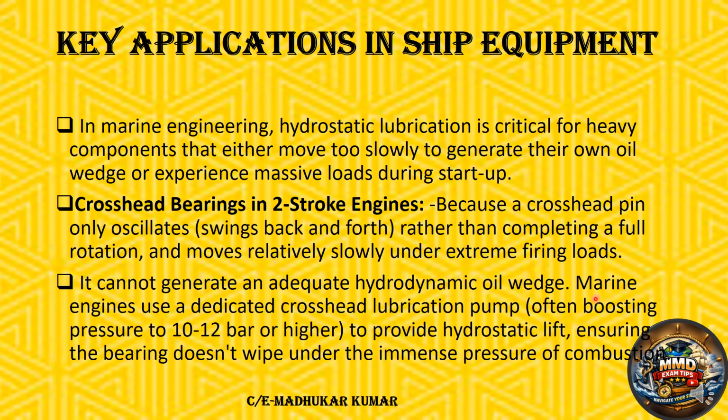So what happens? Marine engines generally use a dedicated crosshead lubrication pump, often boosting pressure to 10 to 12 bar or higher to provide the hydrostatic lift and ensure the bearing does not wipe under the immense pressure. So this is one of the examples, but I am not completely sure about this dedicated crosshead lubricating pump. Earlier it was there. I have seen it in Sulzer engines and all.